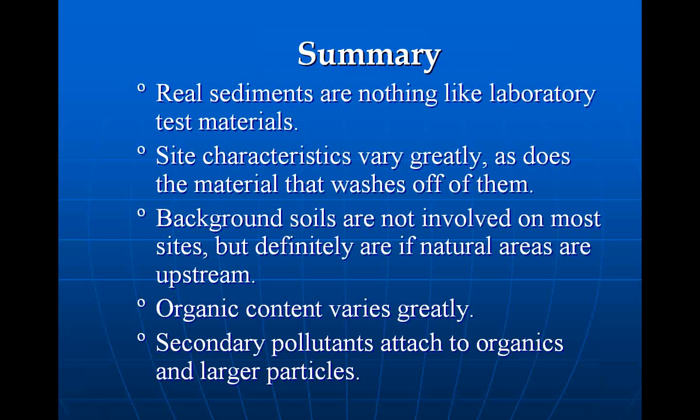There's a lot made of surface area. Oh, clays are important because they carry the most surface area. Well, first of all, you're not going to settle a clay out of water ever. And since it's a micron or two, you're darned unlikely to filter it out either. But the neat thing is particles that size like to stick to other particles. And the more rough the surface of the larger particles, it's very easy, and this has been proven, and I didn't do the research myself. There's 2 or 3 papers out there if you want to look them up that show that on average 30 to 50 micron particles in nature have higher surface areas than the more rounded clay particles at 1 to 2 microns.